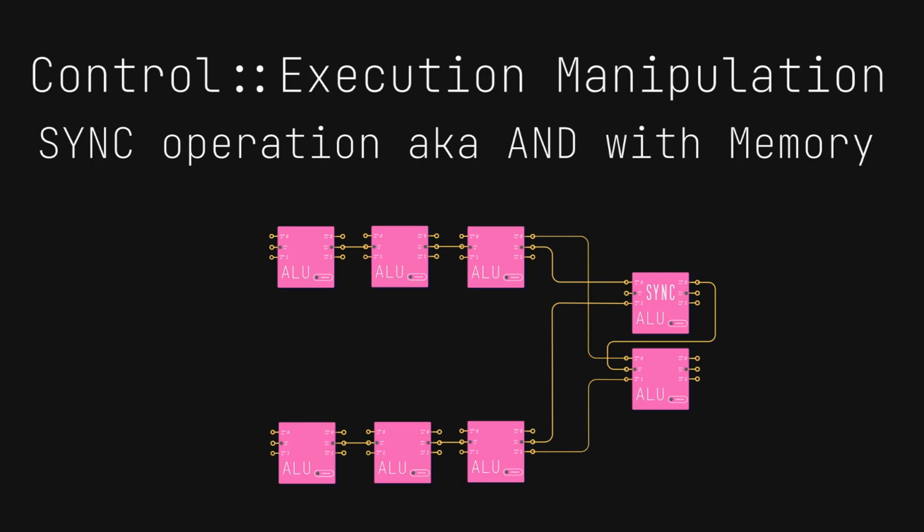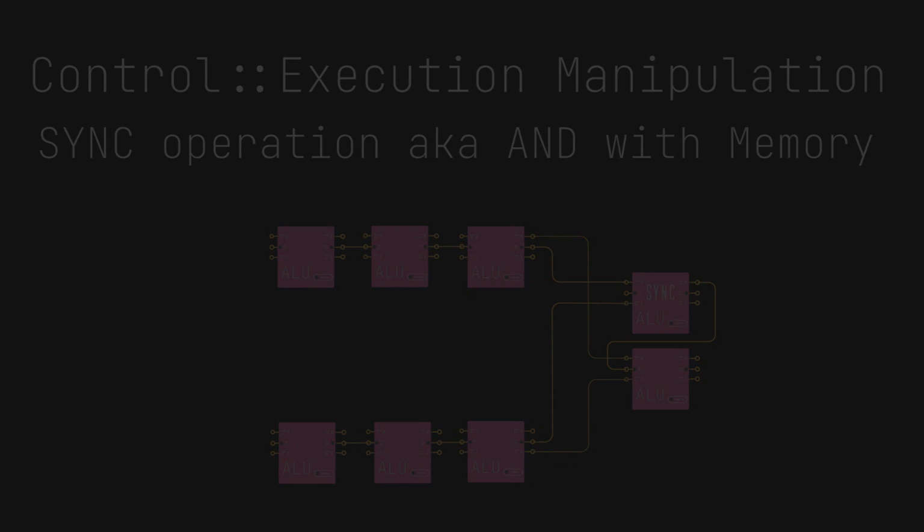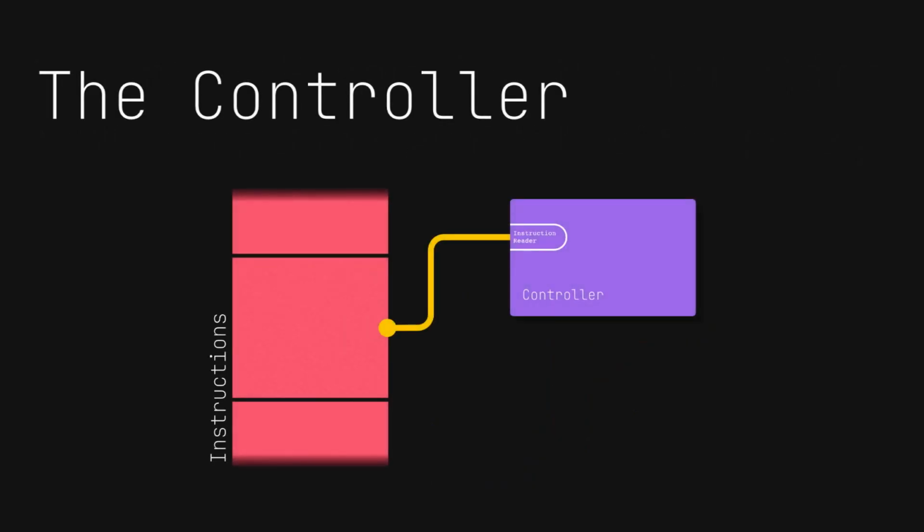We could use an AND operation on the activations, but remember, the activation signal generally only lasts 1 clock cycle in a specific place before moving on. So if the inputs are not perfectly synchronized, the rest won't execute. To fix that, we add a small memory to the AND operation. Now, it is going to remember that one of the inputs has been set when the other goes high, and that we can continue. Lastly, we need a controller.